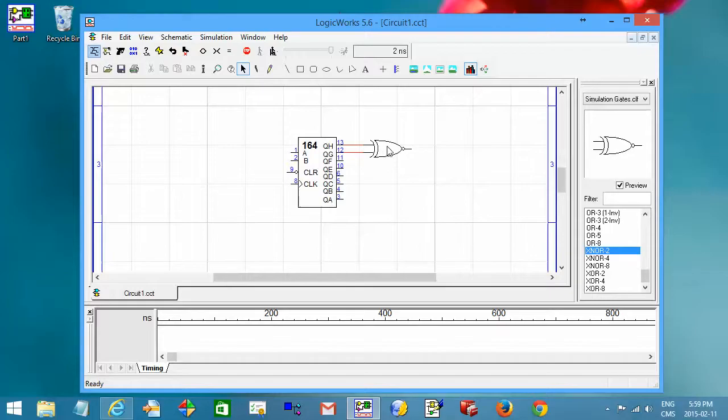Now I'm going to actually create a signal. Again, it's going to figure that out because we're going to go to the end of a pin and drag from the end of a pin. That means we want to draw a signal. So we just drag it up to here, and then we let go of the mouse, and there's that signal created. Now if I go down here and click on the end of this pin and drag up to that point, the two are connected.